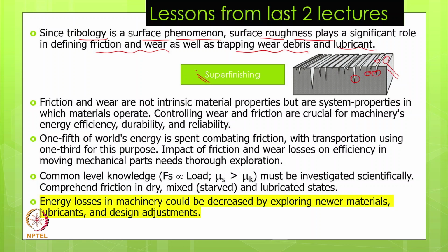This can be achieved by a super finishing operation. If we are not able to do the super finishing operation because of manufacturing limits, then a rigorous running-in process is really required, a meticulous running-in process is really required.